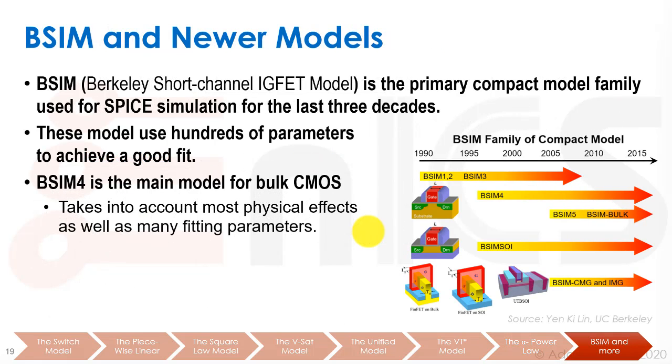But again, this is also not accurate enough. It's nice for hand analysis, but when we have a computer and can run heavier simulations, we want something very accurate. We don't want to tape out our chip for millions of dollars with inaccurate models, and that's where BSIM, or Berkeley Short Channel IGFET models, came in. The BSIM group at Berkeley came up with a very, very complex model that takes into account all of the physical properties and allows a lot of fitting parameters in a compact model that can be plugged into SPICE and used for simulating a transistor.